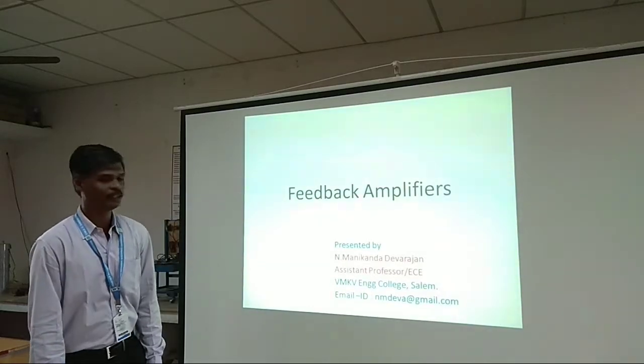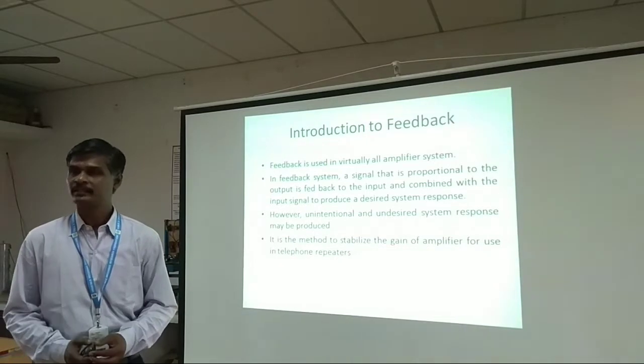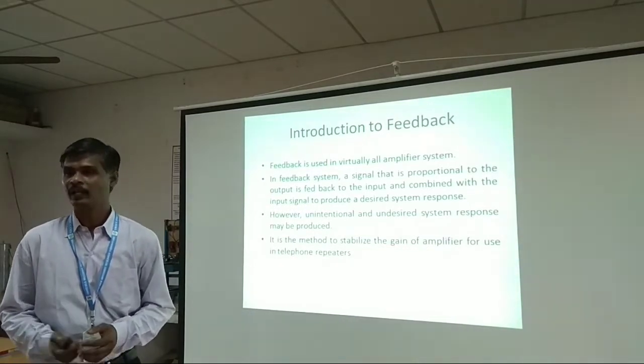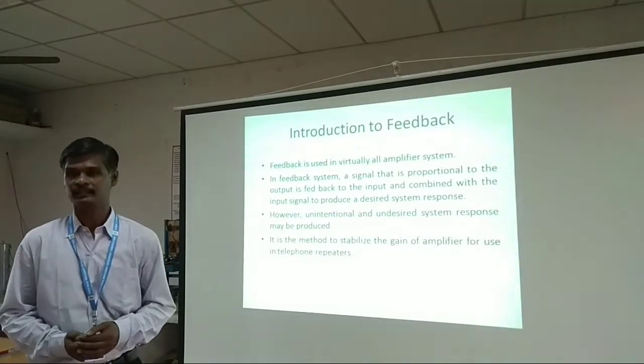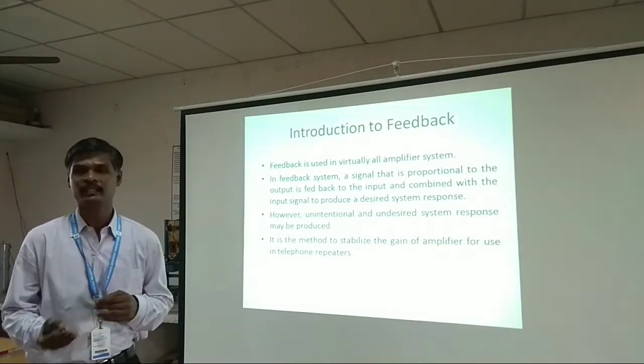Today we will discuss about feedback amplifier. Let's see the introduction about the feedback. Feedback is used in virtually all amplifiers. Why do we use feedback in the first place? In order to reduce the gain, at the same time the bandwidth can be increased.